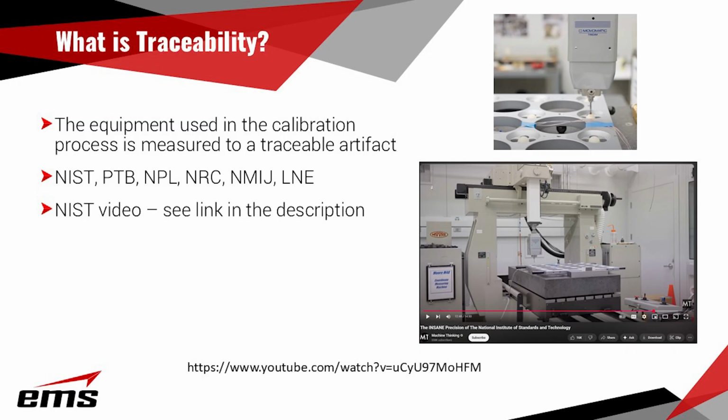So then when you send your equipment in to be calibrated, they are going to use that artifact and measure your system to it. So that traces all the way back to NIST in this case, okay? So that's what a traceable artifact is. If you're getting your equipment not calibrated to a traceable artifact, I would just be careful. I'm not saying it's the end of the world, but if you're trying to do precision metrology, it's really kind of important you do that. If you're not doing hardcore metrology, maybe it's not as important. You definitely want it measured to an artifact, but you really want to look at where you can trace that artifact back to, okay? So that's what traceability means.